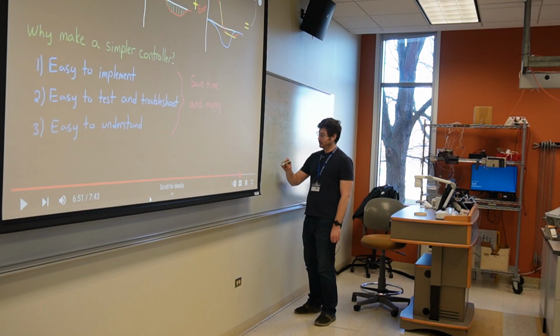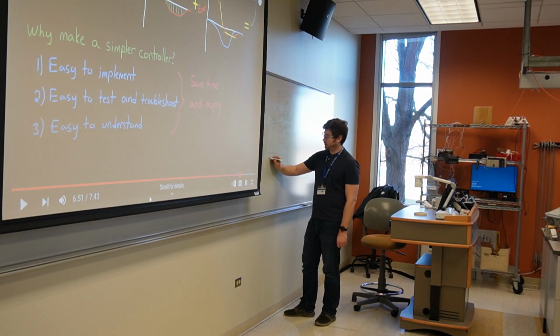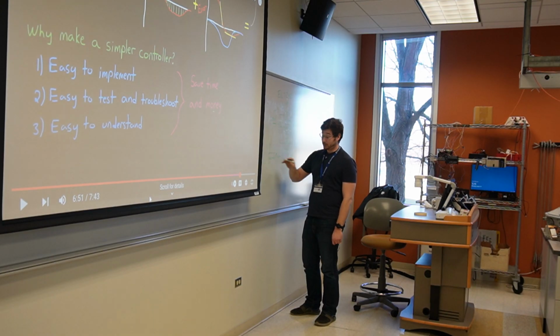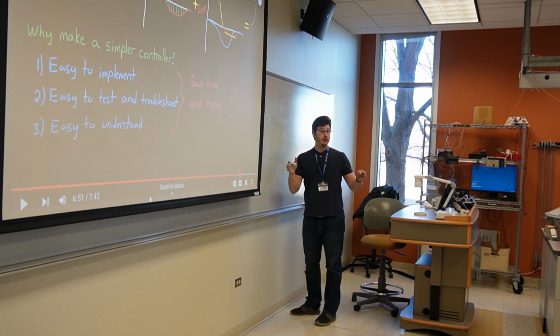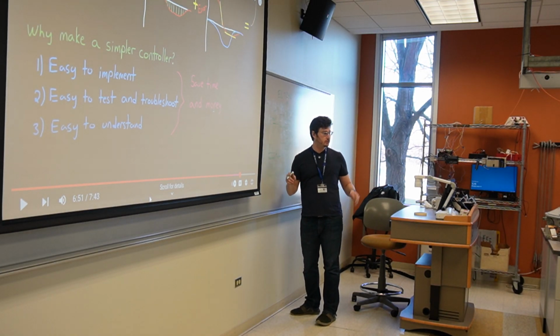The way that integral controllers work is that it continually adds up this little error. It'll add this error to this error to this error at every instant in time, so the sum will start to grow over time as we keep compounding these errors.